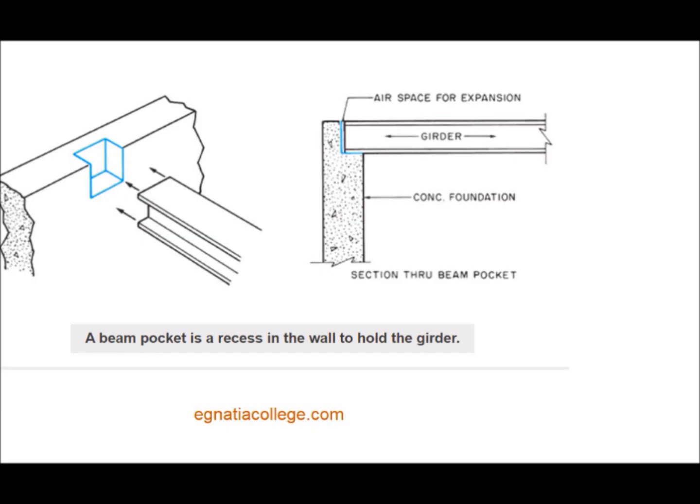The foundation may include pilasters for extra support. A pilaster is a thickened section of the foundation, which helps it resist the pressure exerted by the earth on the outside. The location and size of pilasters are shown on the foundation plan.